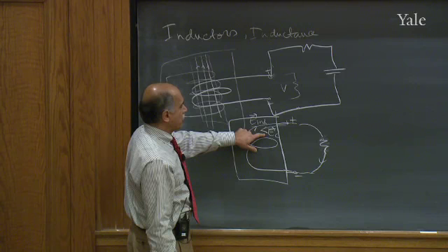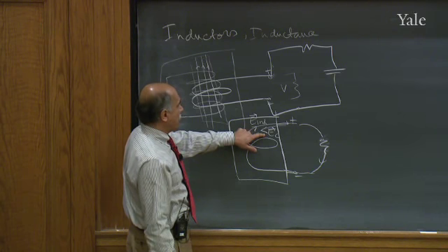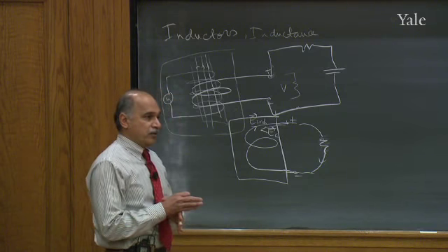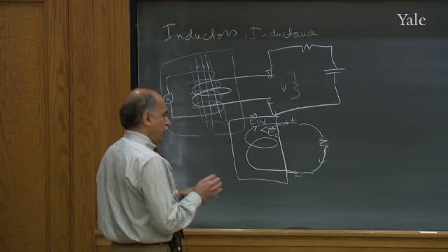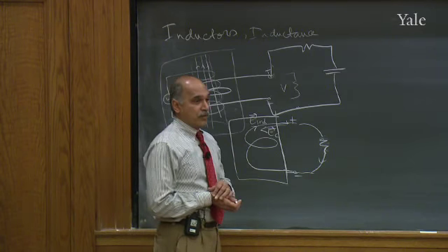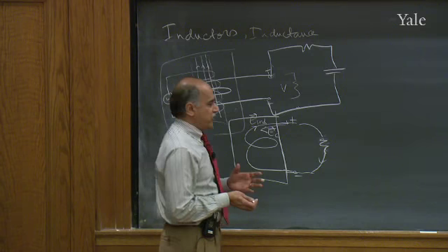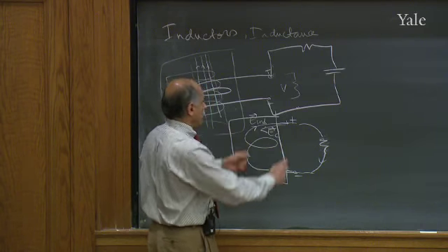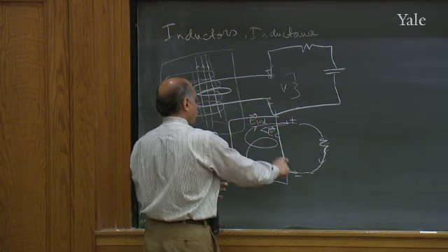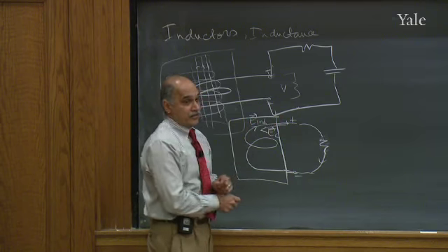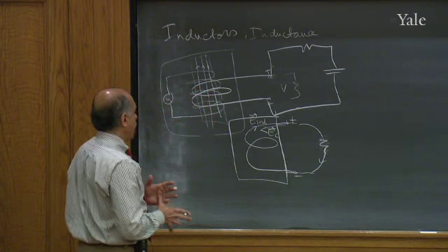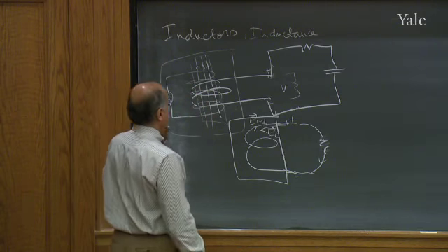So you really should not use the laws of Coulomb for this problem, but it turns out, even though Coulomb's law is strictly valid only for fixed electric charges, as long as the velocities required are not too big, you can continue to use Coulomb's notion of an electrostatic force. The basic question is, you're telling these charges to constantly rearrange back and forth. First you want this terminal to be plus, a short time later you may want that to be plus. How quickly can they rearrange? That's connected to something called the plasma frequency of these materials. And unless the frequencies are like 1 trillion, you don't have to worry about it.